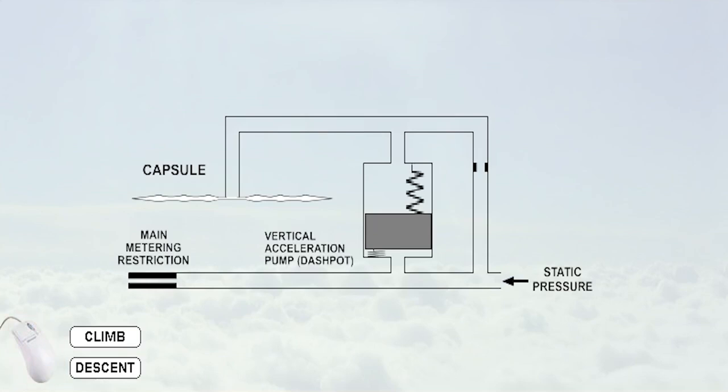If the vertical acceleration ceases, after a few seconds the piston will slowly rise to its original position. But by this time the correct differential pressure between the capsule and the case will have been set up, and the correct rate of climb will continue to be shown.